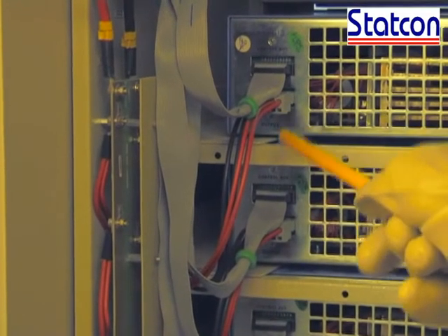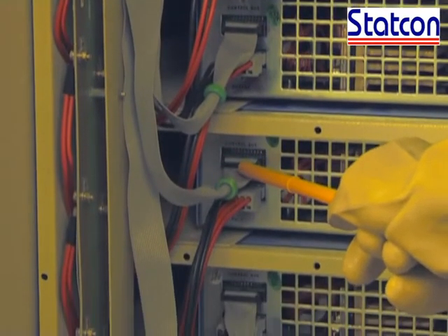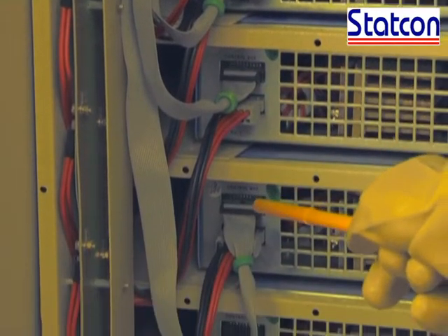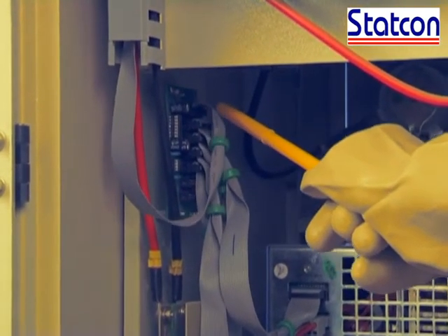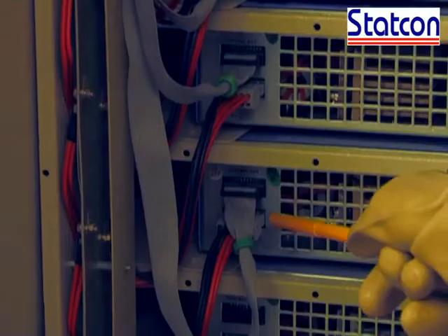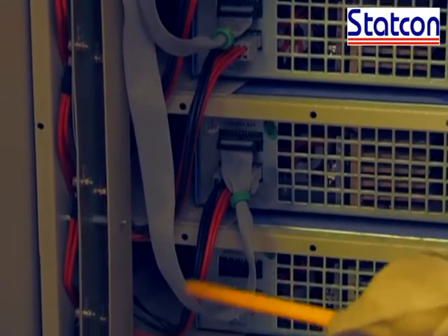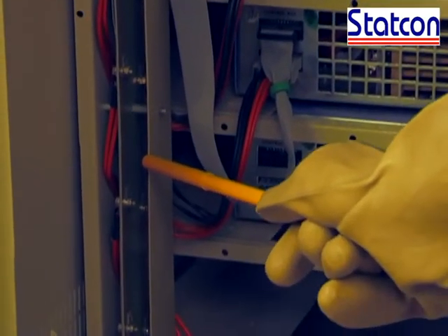110 volt DC output of all the SMR modules is drawn from these connectors. A control cable is also connected with each SMR and all the cables are connected to this sharing card. And the final output of all the control cables is given to the DSA. Output of all the SMRs is given to this common bus bar.